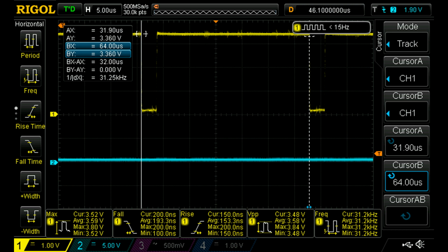After the change, the horizontal frequency hasn't changed. We also had to tweak some of the parameters for the line count to get the syncs correct and the video active correct. And here's what the monitor looks like after the change. As you can see, the video is stretched from side to side of the screen. It's not stretched vertically because that's a line count issue.